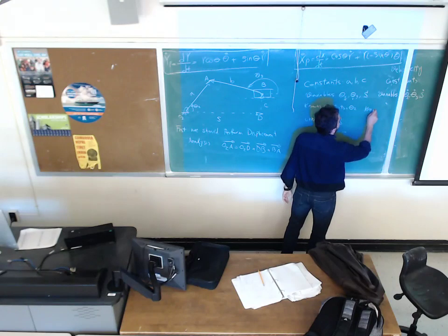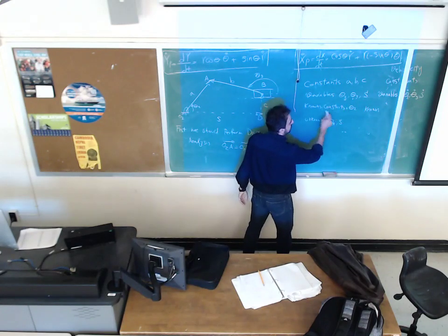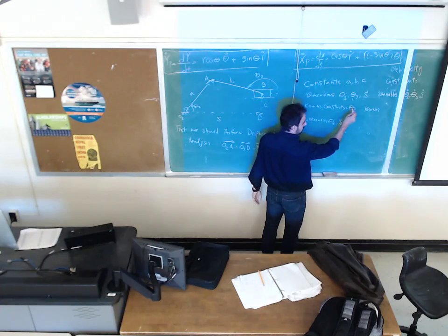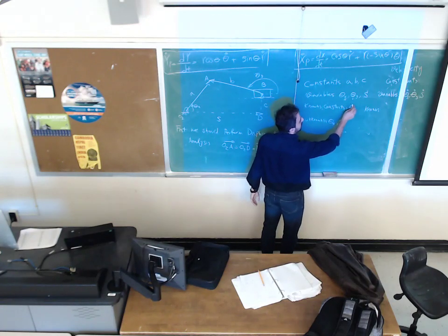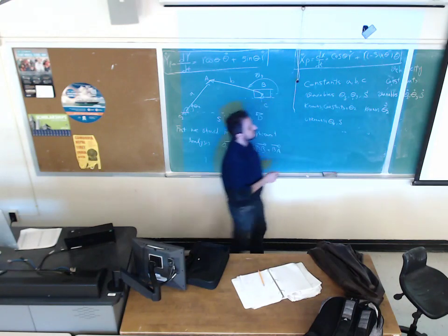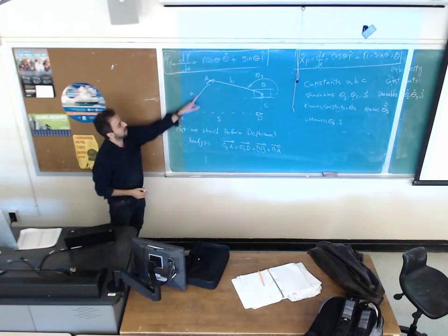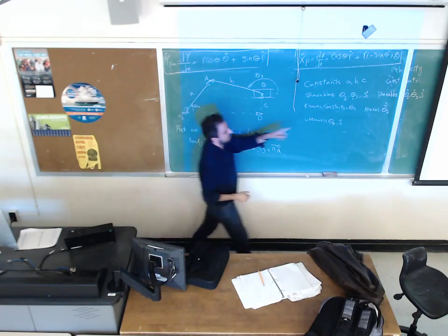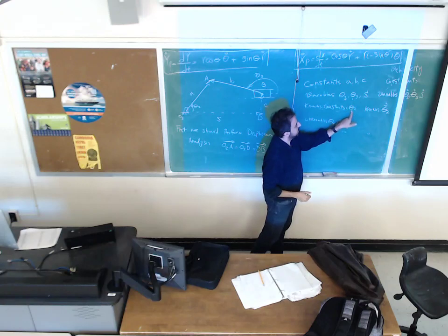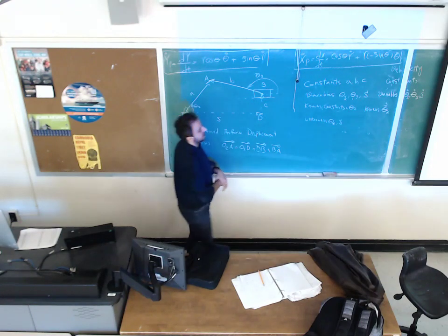Knowns are constants plus theta 2. Put a dot on top of this. Theta dot 2 should be given. You should know what would be the velocity of the input link. Whatever is the input variable here, its derivative should be known over there.